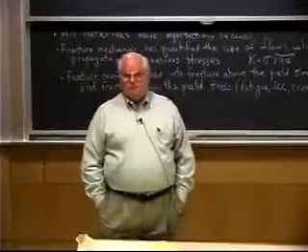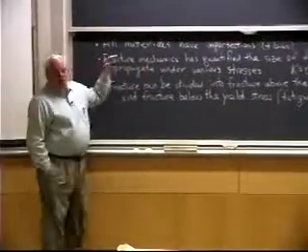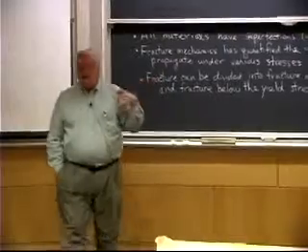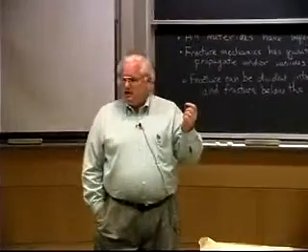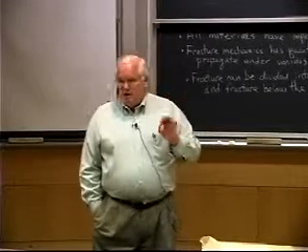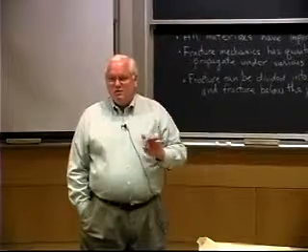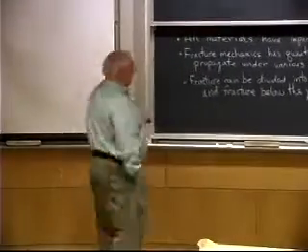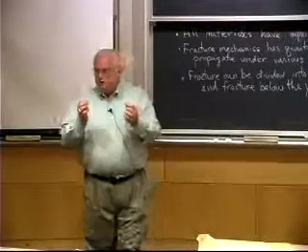Okay. Last time we didn't talk about the first point here, but let me just point it out, that all materials have imperfections. And if we're talking structural materials, we're interested in imperfections bigger than the atomic scale. If you're talking functional materials like photonic or electronic materials, you may be interested in the imperfections on an atomic scale. An actual vacancy or a substitutional atom in a silicon or something will control the functional properties. But the structural properties, it's those little notches like in the piece of paper that control the properties.